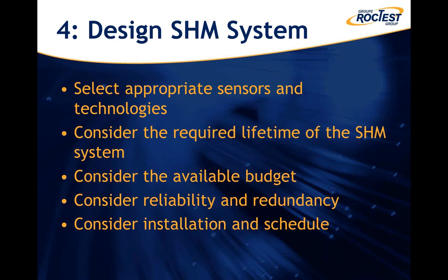This is also the right moment to consider reliability and redundancy. So if some sensors are very critical, it's important maybe to double them or to have two different measurements leading to detecting the same risk. And planning for installation and schedule can also be started.